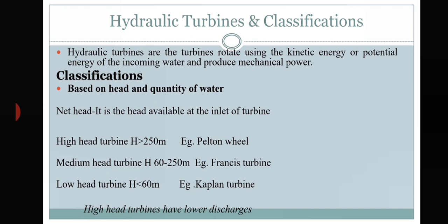So Pelton wheels generally are employed in dams where the dam will be located at a very high altitude above the sea level, and also the dam will be having a much height from the ground, and your power generation plant will be kept at a lower part somewhere kilometers away from your dam. Say for example our Idukki dam is having a Pelton wheel. The power generation wheel is actually kept at your Moolamattom area, which is at the lower part of the Idukki, and the dam, you will be knowing that the dam is at a very high altitude above the sea